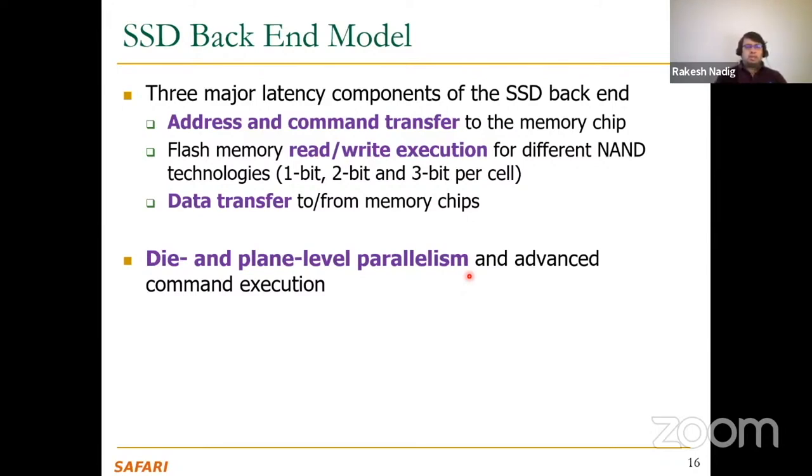There are also other advanced command execution modes, such as multi-plane operations, as I said, and copy-back operations, where we don't transfer the data back to the host itself; it's kept in the buffers within the device and then moved back to the flash chip.